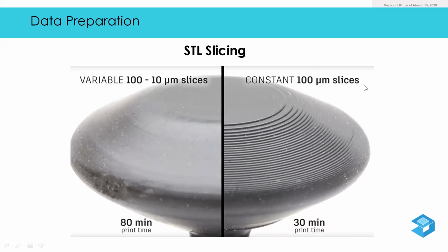You would optimize your slicing in such a way, let's say take 50 to 60 micron for this part, and make a part with a better finish. Then you can do some form of post processing, as I had mentioned in the previous webinar. You can sand this component, and then you can use it.